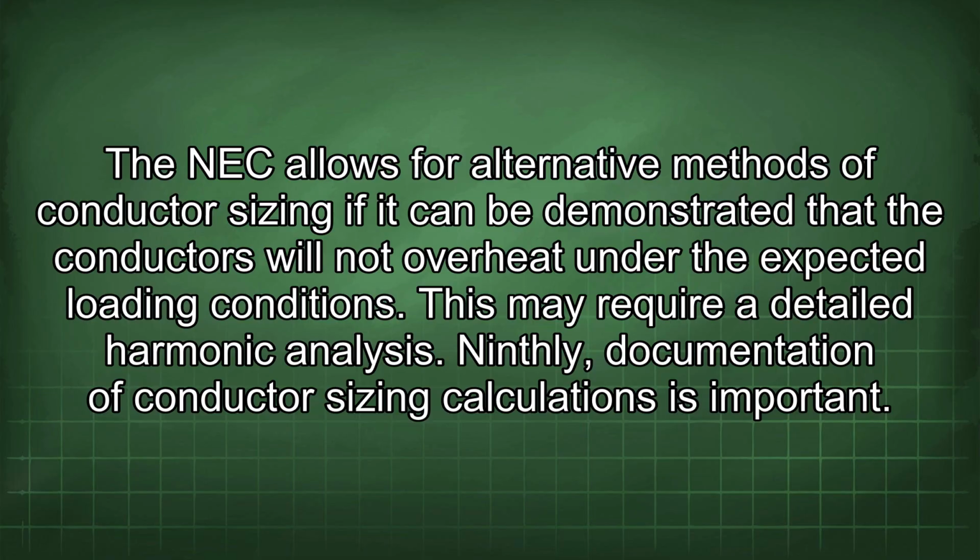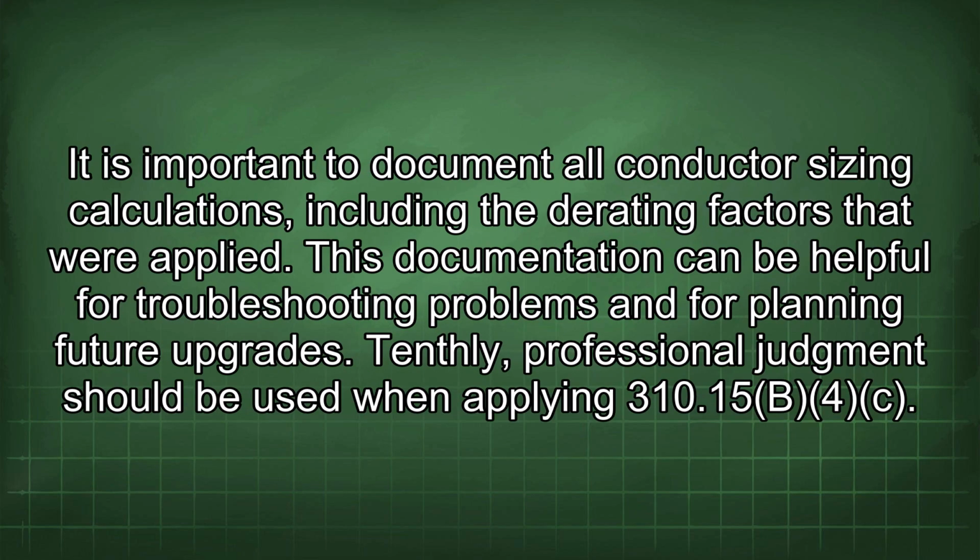Ninthly, documentation of conductor sizing calculations is important. It is important to document all conductor sizing calculations, including the derating factors that were applied. This documentation can be helpful for troubleshooting problems and for planning future upgrades.